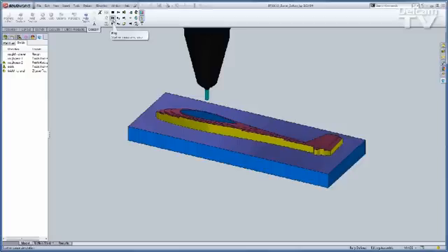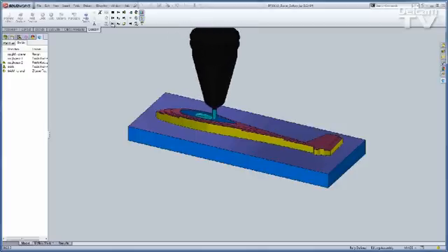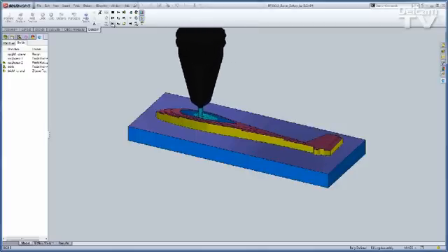And again, this is the traditional top-down. What's going to happen is the tool kind of starts in the middle with this particular shape. So it's cutting with the center of the end mill and it's kind of pushing its way to the outside. So with this type of geometry, this is probably not the best approach.